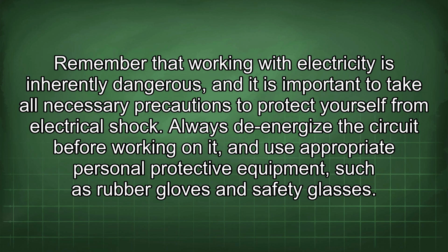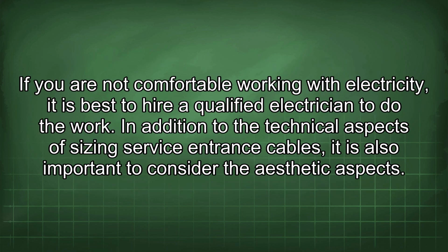Remember that working with electricity is inherently dangerous, and it is important to take all necessary precautions to protect yourself from electrical shock. Always de-energize the circuit before working on it, and use appropriate personal protective equipment, such as rubber gloves and safety glasses. If you are not comfortable working with electricity, it is best to hire a qualified electrician to do the work.